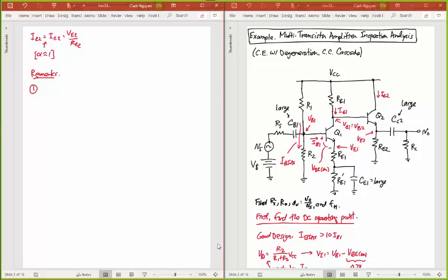Or you look for something that has a definite resistance and a definite voltage across it. And once you find that, that's what's generating your currents. So in this case, you're looking for resistors, but basically you're looking for well-defined voltages. And in this case, that's what VBE on is. So part of the remark here is you have to look for VBE ons, right? Because these are well-defined voltages.